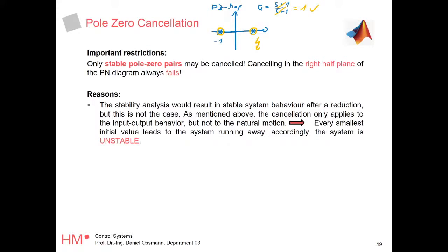These are the explanations. Because you will have an unstable system. As I said, we are working with linear systems. All these PD2, PD1 systems are an approximation of our real world. In reality, our system is a little bit more complicated than this. When we cancel a pole with a zero, because our transfer function tells us we are canceling something, the pole and the zero might not actually be where they are in our model, because we approximated our aircraft with a linear model.